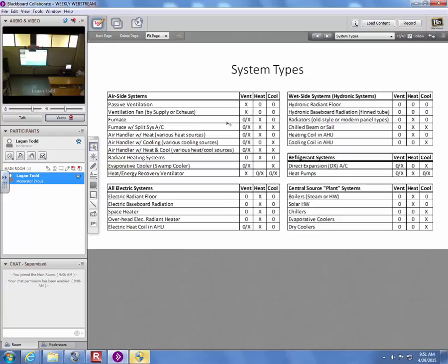Okay? And now we started to see, well, let's put a serious exhaust fan in there that runs a certain amount of time and lets that pull outside air in for ventilation. But you could say, well, we've got this furnace, it's got a blower in it, it's just recirculating inside air. Why don't we put one little duct that goes off somewhere to an intake louver to outside air, and bring a certain amount of outside air into that airstream, and let the furnace blower mix that fresh air with the return air, heat it up and deliver it.